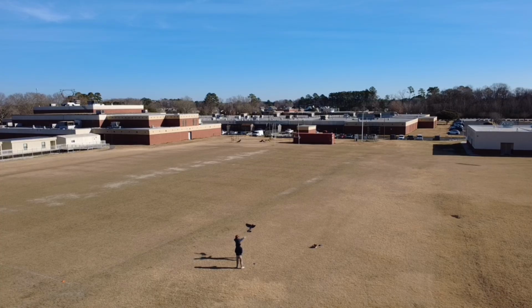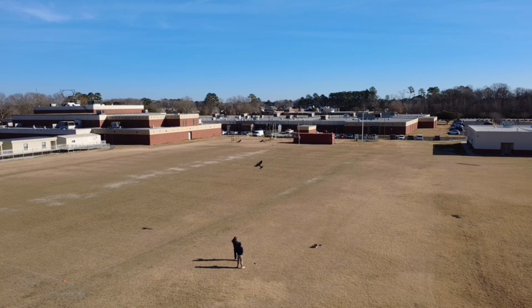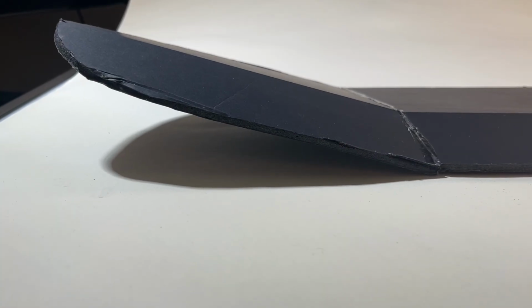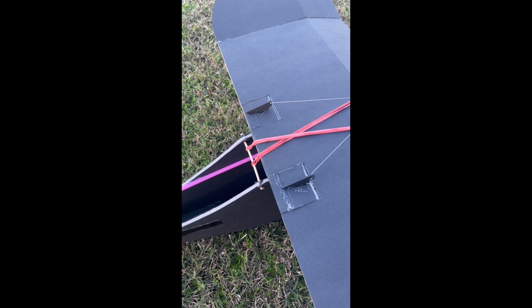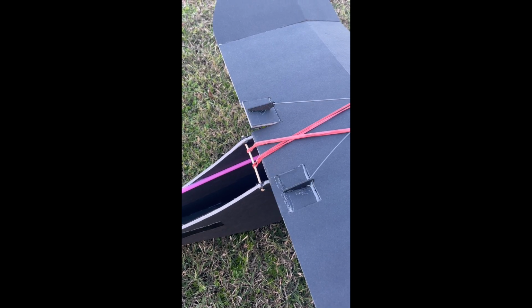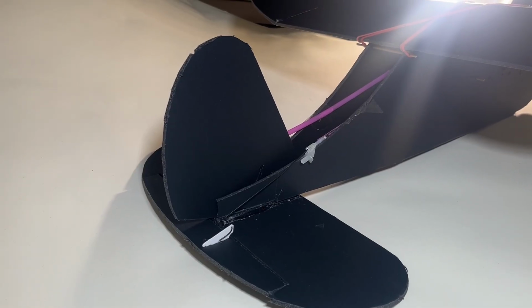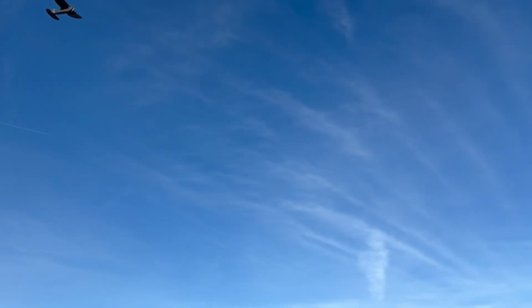On our aircraft, rudder inputs also help the plane bank into turns because the dihedral naturally converts some of the yaw into roll, so turns felt smoother and more predictable. We originally considered ailerons, but we removed them to reduce complexity in both electronics and piloting. With dihedral and rudder-based turning, we could still turn effectively while keeping the control system more reliable for a first-time build.